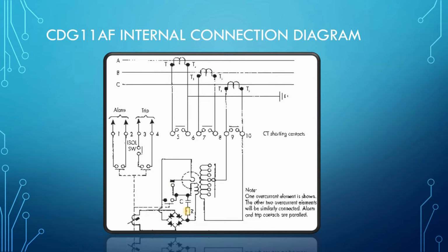Then this coil will be energized, and this one will be short circuited, and that will be the trip signal for the circuit breaker. Generally we know in the circuit breaker there is a trip signal, and it is NO or NC type. That we will see in the power supply or current injection unit where the NO and NC are.